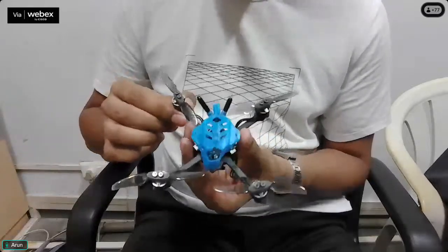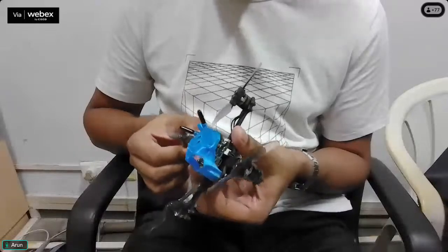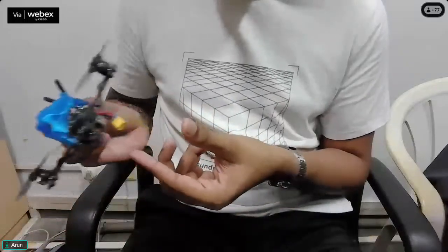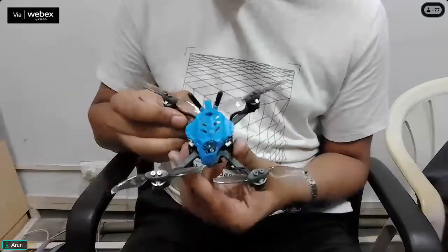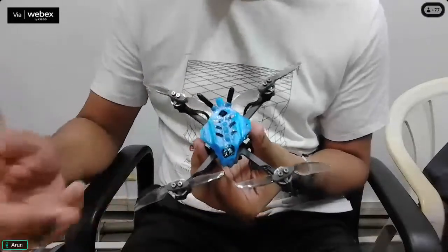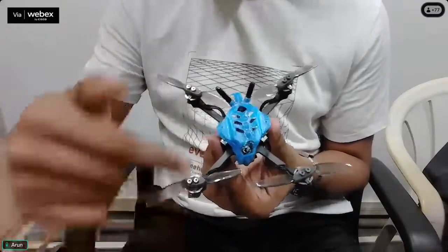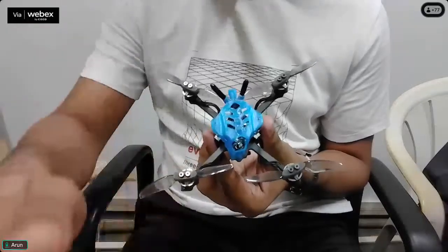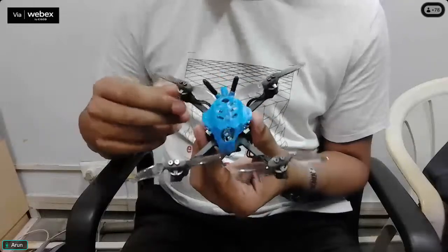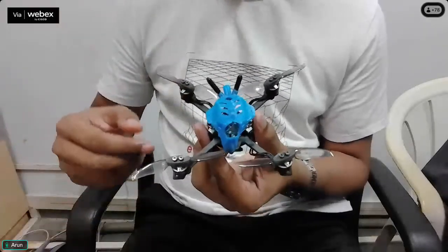Okay, when you pitch or when you roll, the drone won't stay in place, but moves forward or to the left. That is because it doesn't have that independent degree of freedom in the X or Y axis. You can only move in the X and Y axis through rotational motions, through roll and pitch.